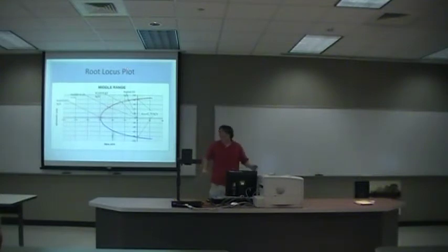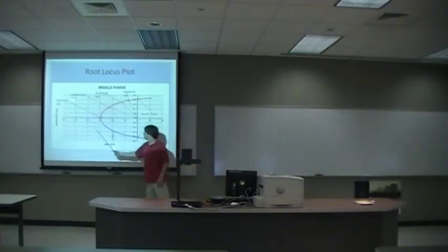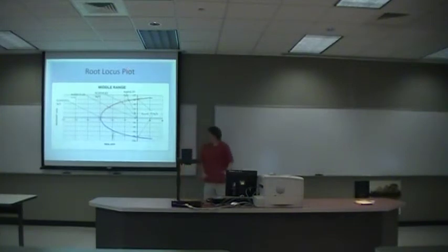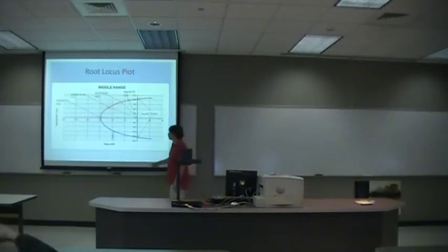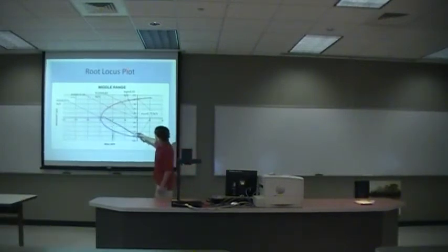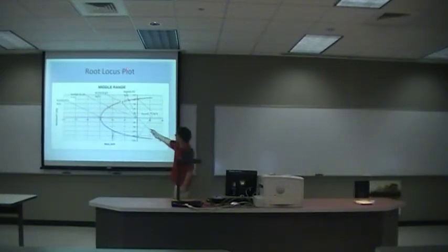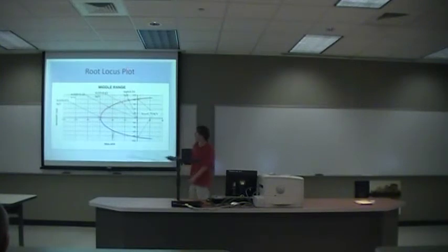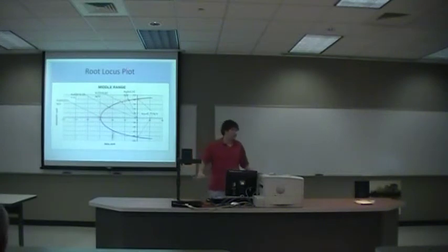But we plotted that up to root locus plots. This axis would be the real axis, and this is the imaginary axis, being that at these points the roots are imaginary. It gave us a critical damping right here, 500 decay, 10th decay, quarter decay, and the ultimate point, where it's relatively monotonic, and after the ultimate controller gain, the oscillation never really dies down and never really stops fluctuating.